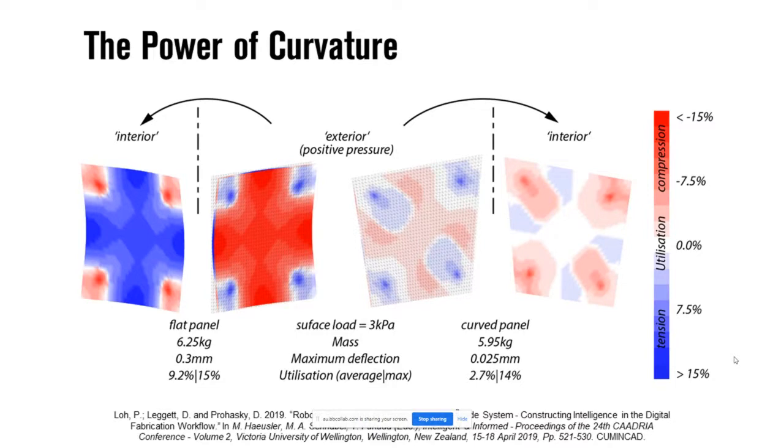This example has a curvature of about 20 meters radius or so, which is very subtle, and it increases that stiffness significantly. That's because of that arching action and the span to depth ratio that's increased. The stress relationship, that's around about a factor of 4, thereabouts, 3 or 4, reduction in the distribution of stress, which is quite helpful for those connections where you've got high stress points.